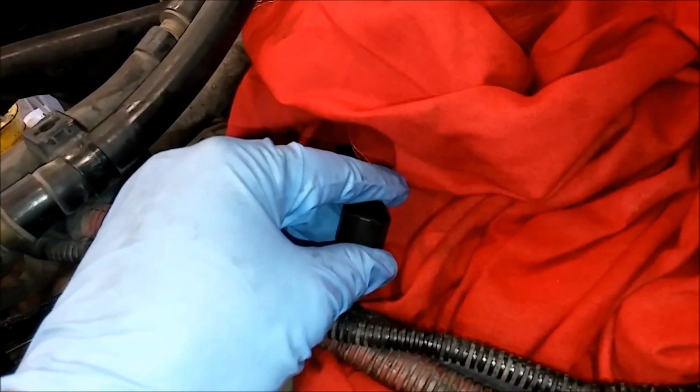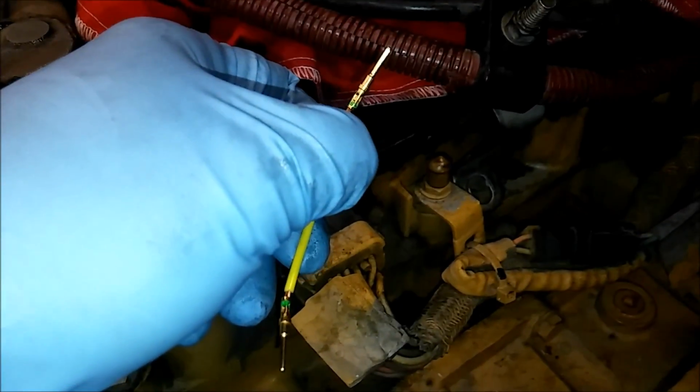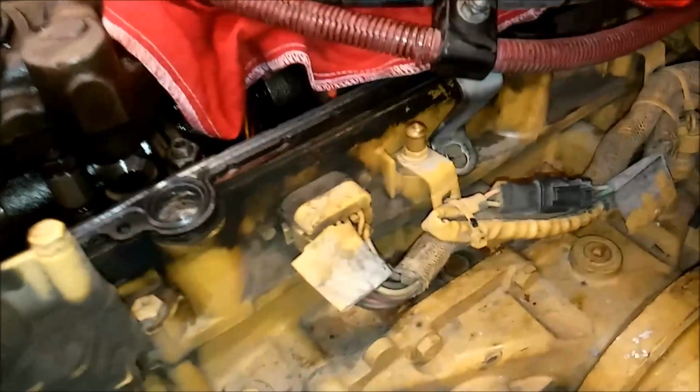Like I said, the key has to be on, and you have to be hooked up with either some sort of scanner or CAT ET. So your injector harness would be the next point. Say you shorted it and it didn't show voltage low. Well, then you would short it at the connector here for your injector harness, which has that sensor wiring going to it.